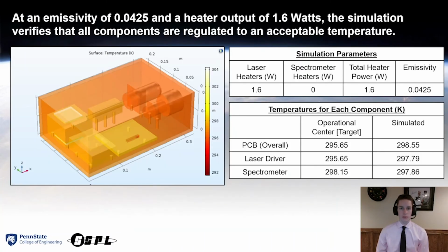This simulation was used both for determining the most desirable emissivity for the passive heating system and to verify that components could be regulated to an operational temperature in a PSR environment while still using under the 3.3 watts of allotted power for the heaters.